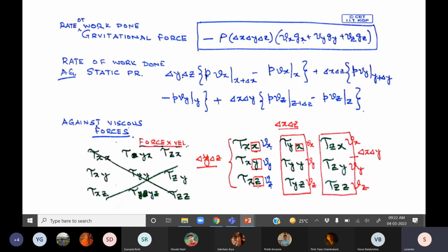So therefore, viscous dissipation need not be considered for such cases, and you would have an almost imperceptible change of temperature when you measure the temperature of water over a 1 meter pipeline. You wouldn't sense any increase in temperature. But if it is done on a microfluidic scale, when the system length scale is of microns, then even for a small velocity, it could be large and you could sense high viscous dissipation.